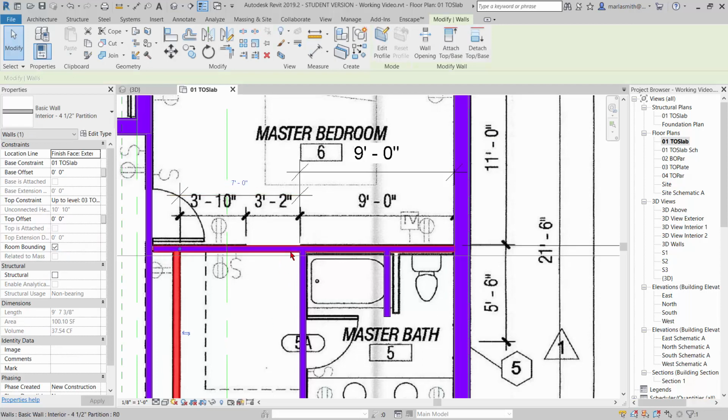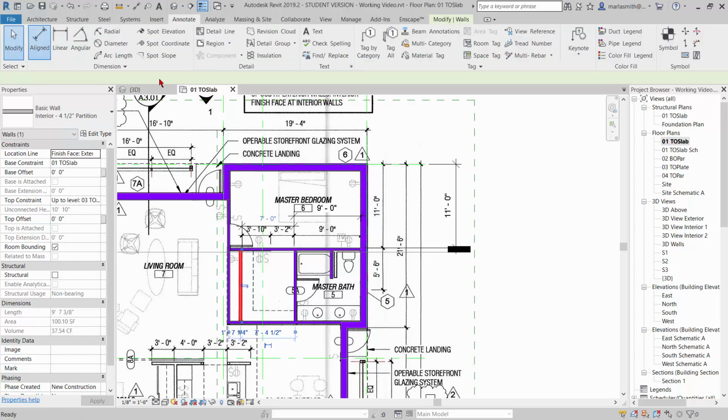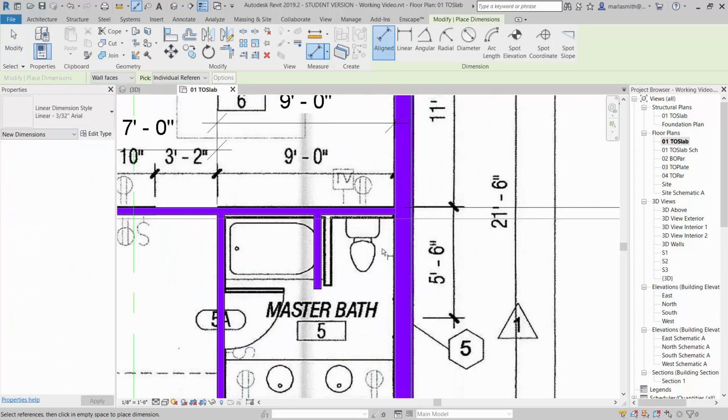Notice that I am going directly through all of the walls and windows. You want to do that. We'll actually put in walls and windows, and it will cut holes for us. So the last one I'll do, this one doesn't have a dimension, but I'm just going to dimension from the inside face of this to the inside face of that.